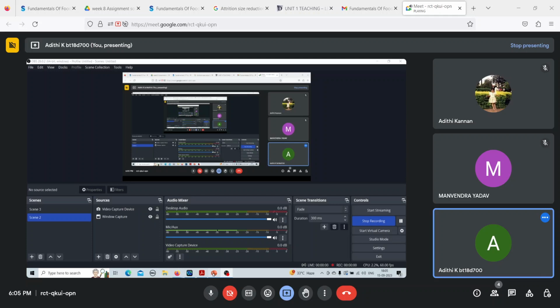But if your speed is extremely fast, then what will happen is you will have the centrifugal force acting on the balls, because of which the balls will not fall down at all. It will keep sticking to the walls throughout if the mill rotates pretty fast. So the critical speed is the speed at which you see this centrifugation effect. That is, the balls, instead of falling down, will keep sticking to the walls because of very high speed.